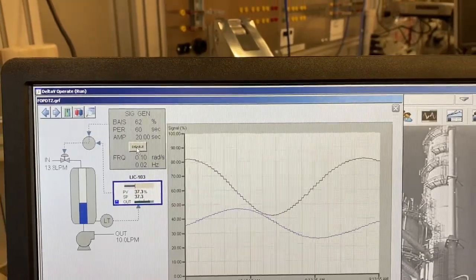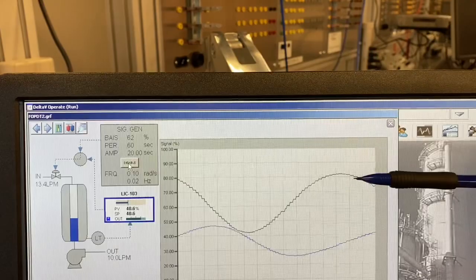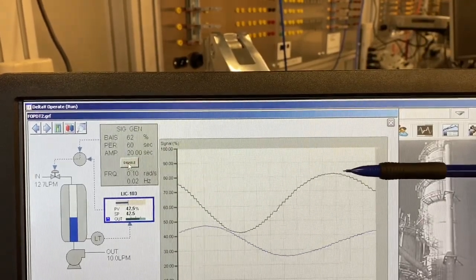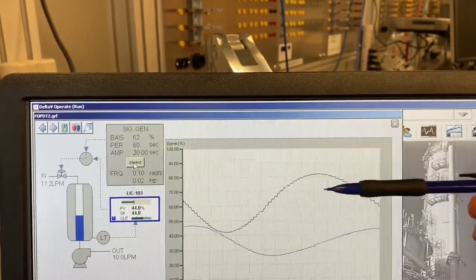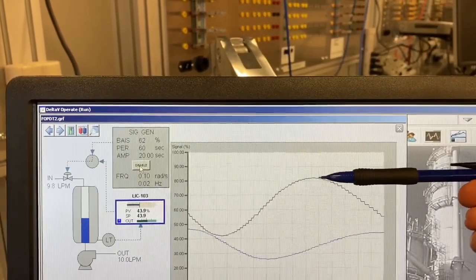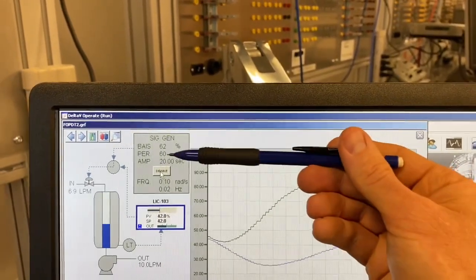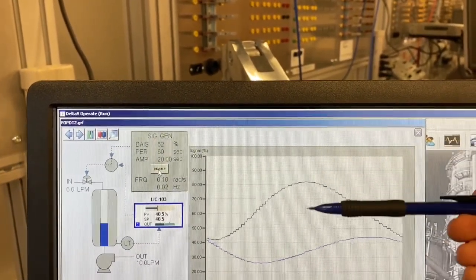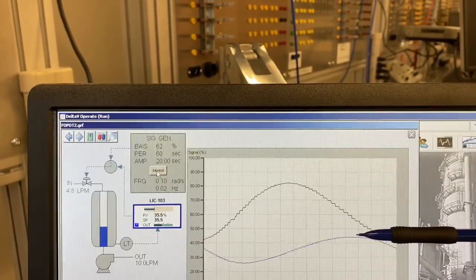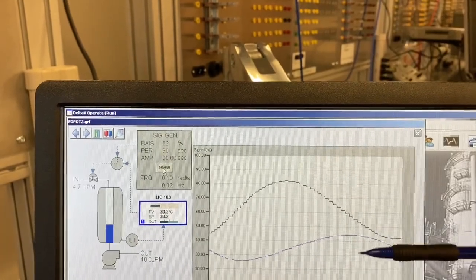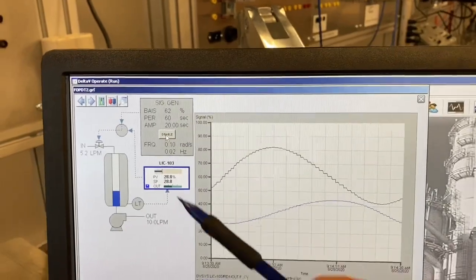And our gain is going to be, this is our input signal here. So this total change, which we said should be about a total of 20 on either side. I guess the easiest way for us to do it is go peak to peak, which would be a total of 40, because our amplitude's 20, so the total difference here would be 40. And if we divide that into the total difference here, then that should give us our gain right now at this particular frequency.